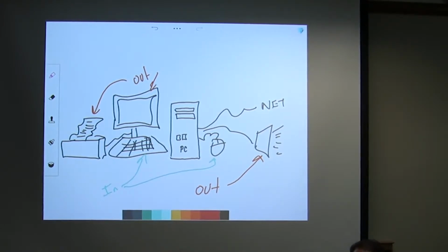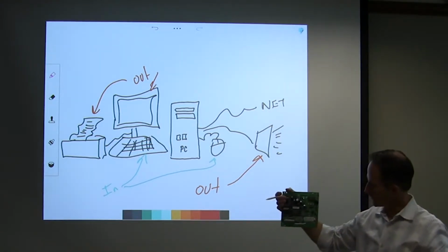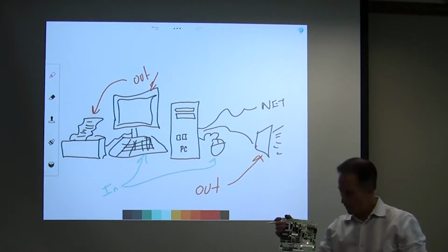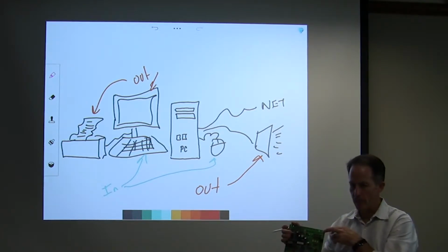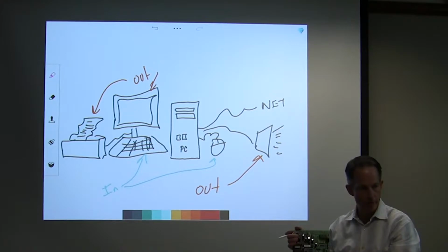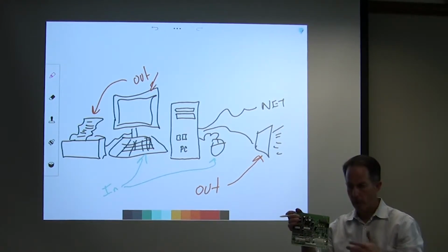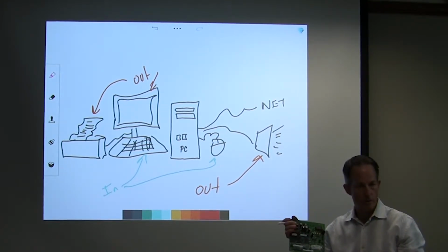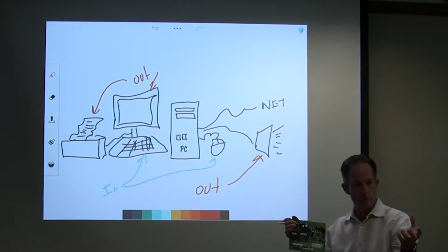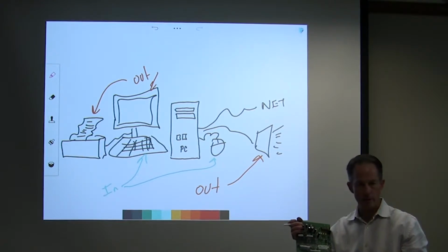Now, before we get too much further, let's talk about just the controller inputs and outputs. We'll say for instance, this is a Smart 2 controller. A little dusty, but it still works probably. So it has some inputs along the bottom, some outputs along the top. What are some of the inputs that we would see on a controller? Temperature, room temperature probe, velocity probe, pressure transmitters. And with those sensors, what kind of signals do we typically get from them?